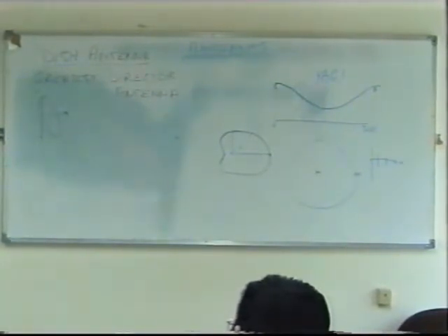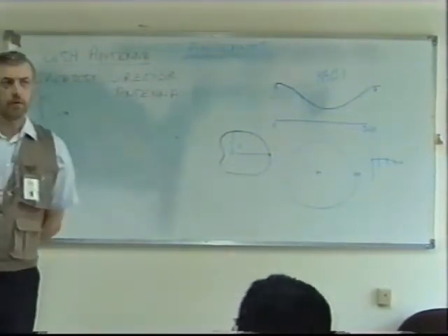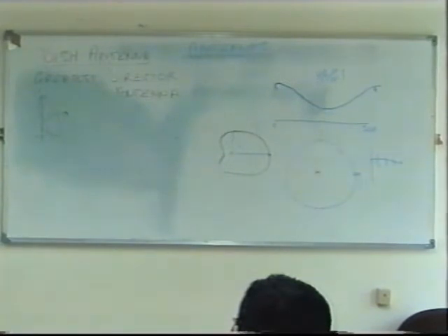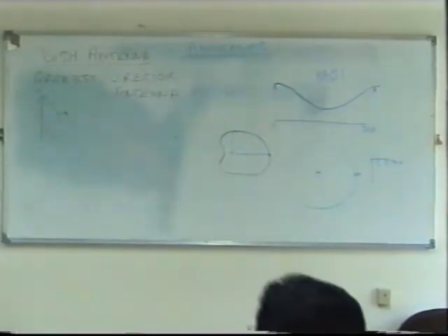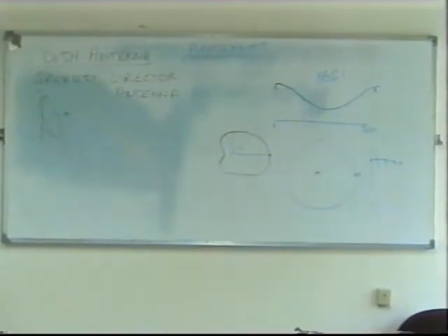Now, what sort of wavelength are we talking about when we talk about microwaves? Very short wavelengths, aren't we? Perhaps even 1 centimetre or so, or less, for microwaves. These very short wavelengths enable us to use quite small dishes. It is actually possible to use a dish for any type of transmission, any frequency, but the size of the dish must be much bigger than the wavelength. If the wavelength gets bigger, then the size of the dish has to get bigger.